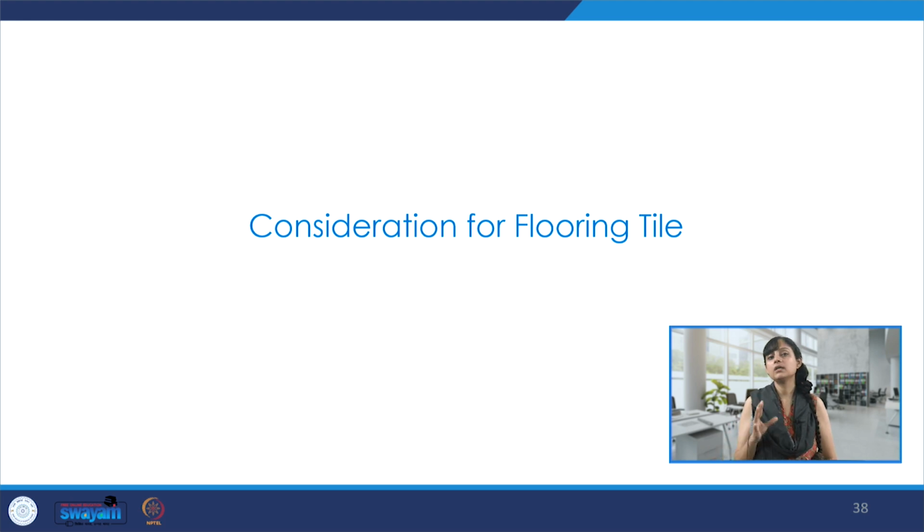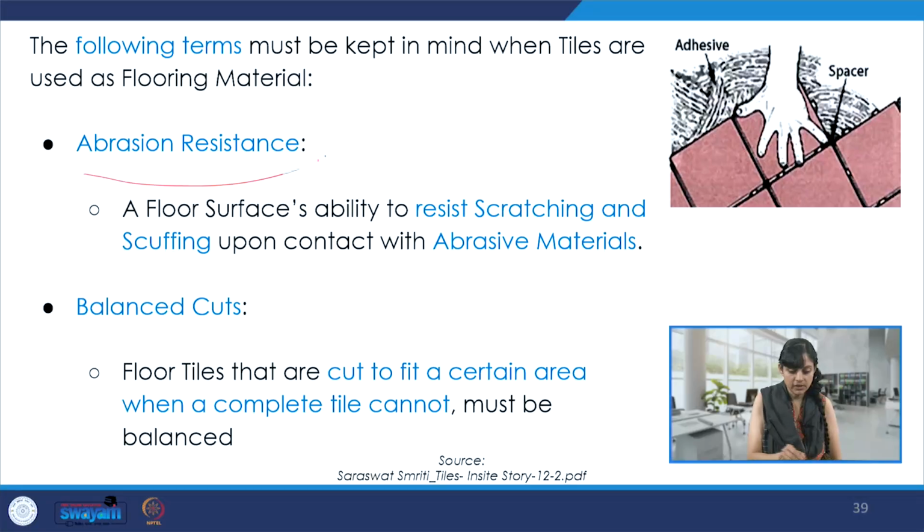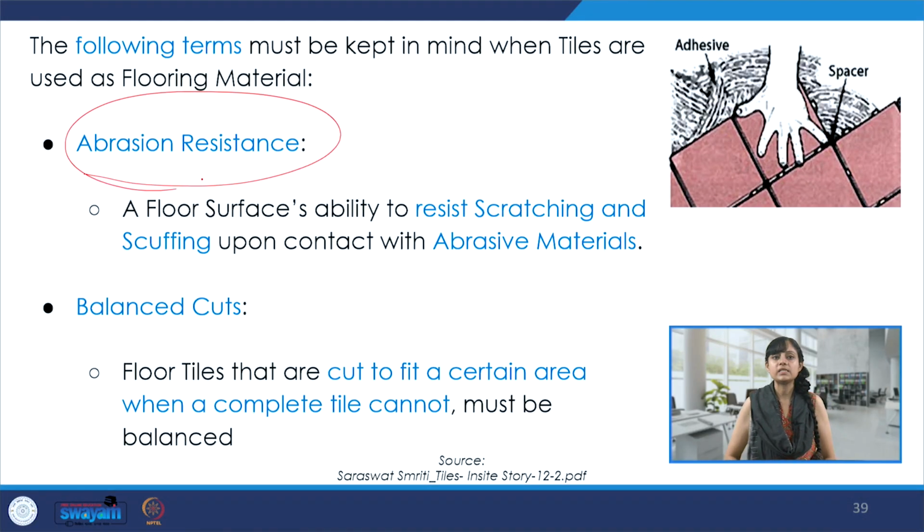Now what could be the considerations when we are flooring tiles, or when we are putting tiles on a floor? These could be some very important considerations, and we must try to understand these terms or terminologies while trying to understand the laying of tiles. So there is abrasion resistance. Basically, a floor surface's ability to resist scratching and scuffing upon contact with abrasive materials. It's very important to understand this.